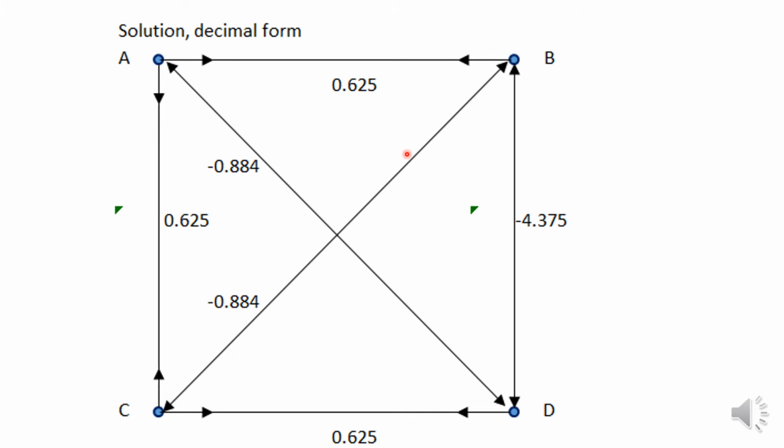So I ask you to compare these methods. Before we go ahead, I just want to mention that there was one external load here, 5 kilonewtons here, and here we see in the member BD the compressive force is a little less, 4.375.